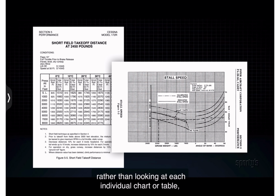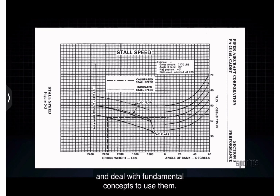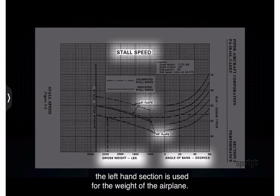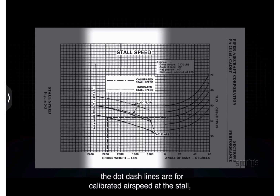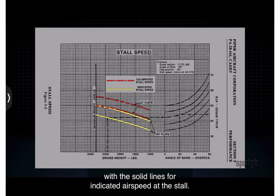Rather than looking at each individual chart or table, let's look at representative examples of each and deal with the fundamental concepts to use them. This is a stall speed versus weight, flap setting, and angle of bank chart. The left-hand section is used for the weight of the airplane. The dot-dash lines are for calibrated airspeed at the stall, with the solid lines for indicated airspeed at the stall.